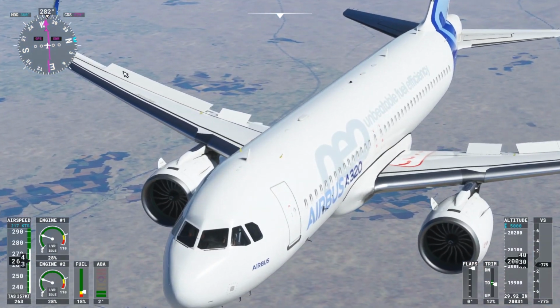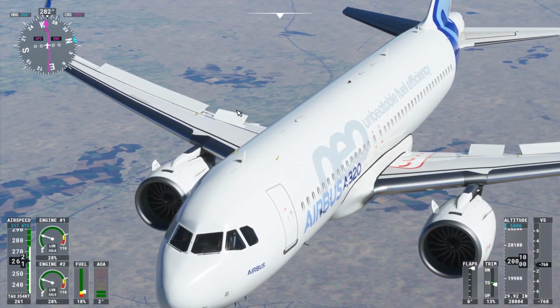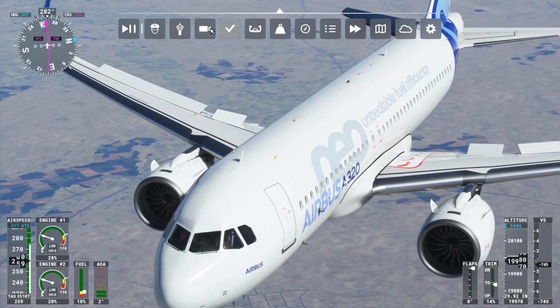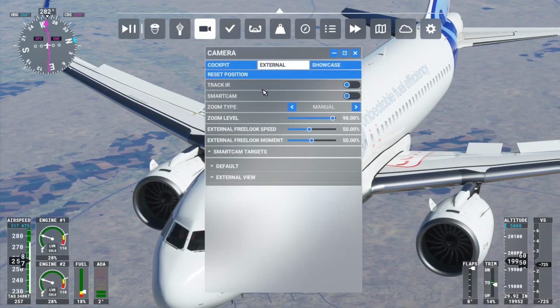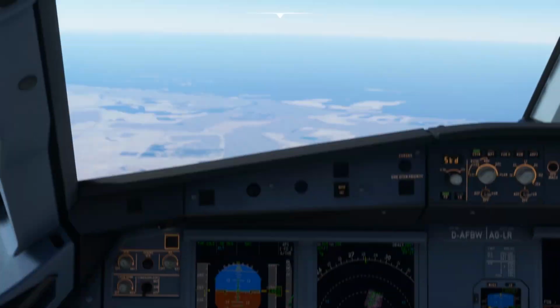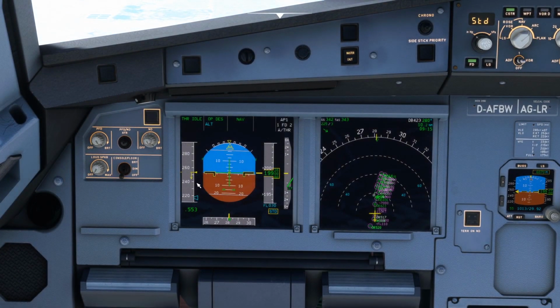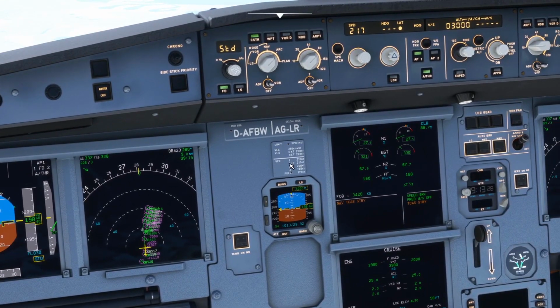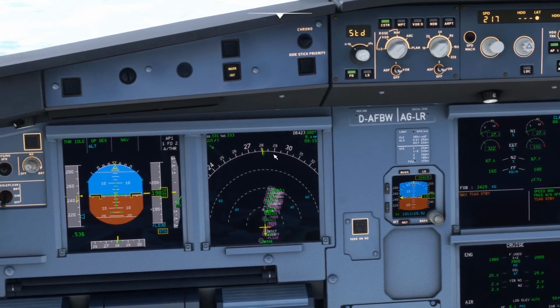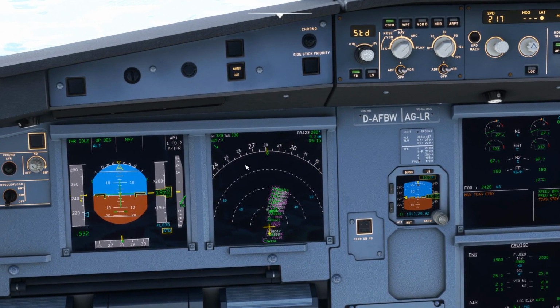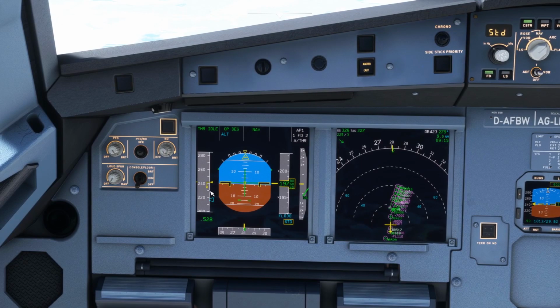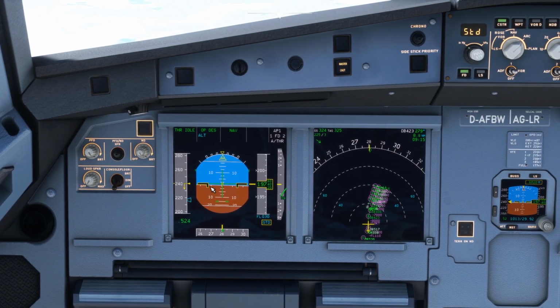You see these flaps coming up, these parts of the wing. This is air brakes. So once the brakes are up, the plane is reducing. You can see the drastic reduction in the speed. And with this, I can take the flaps, and the flap settings are given here. At 230 knots, you can take one flap. So below 230, I will get one flap.